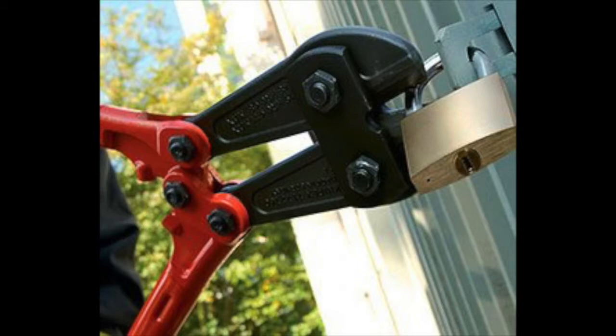It must also withstand shear force supplied by bolt cutters, which is approximately 20 kilonewtons when 250 newtons is exerted at the handles by a person. So a high shear strength and a high shear modulus are necessary. The shackle must also have a high toughness, so it cannot be shattered by a sudden impact, such as the impact from a fall. And the shackle must have good corrosion resistance, so it can withstand harsh outdoor environments where it'll be in use.